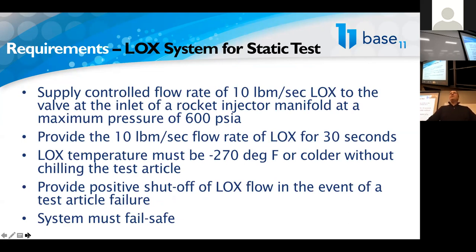So there may be any number of reasons why you don't want to flow your propellants through your injector to chill your plumbing system. So we have to come up with some way to chill your plumbing system without going through your test article. In the event that your test article, your engine, blows up or has some sort of failure, we want to make sure that we don't have to dump the entire contents of the run tank out onto the ground or into the fire or whatever the case may be.